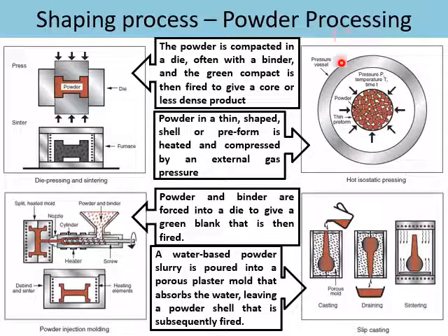The powder injection molding over here applies similar principles as plastic injection molding. In this case, metal powder is mixed with the binder, poured into the screw heater, and pushed into a heated mold to a desired shape. The shaped material is then sintered at high temperature to reduce the pores in the product. Last but not least is the slip casting method, usually for ceramic hollow shape production.